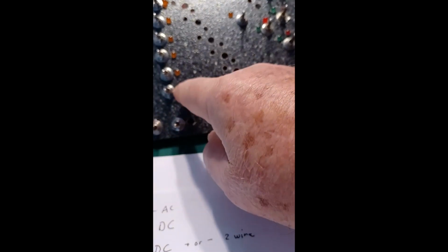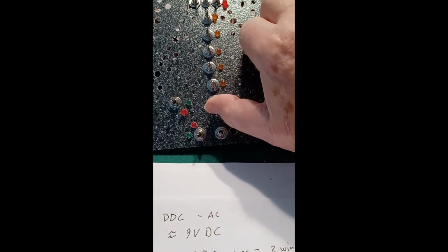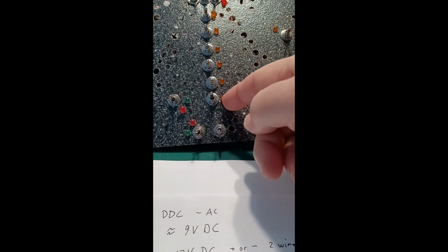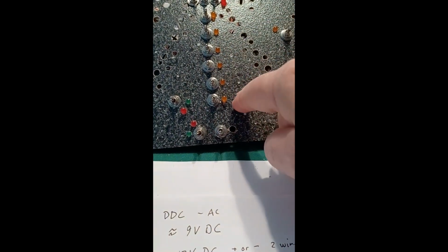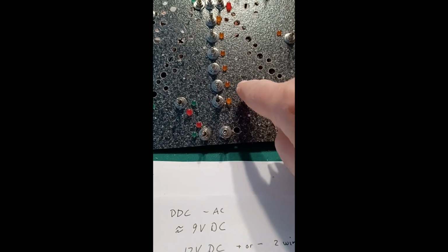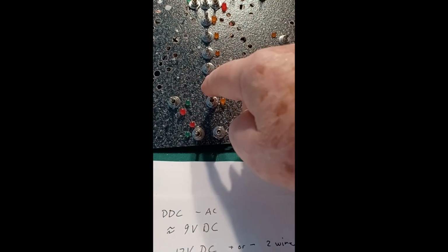These switches to the block sections, though, are not. They're on-off. So if I flip it up, it stays up. With the switches to the block sections, when I turn a block section on, the amber light will come on showing you that block section is energized. That's simple.